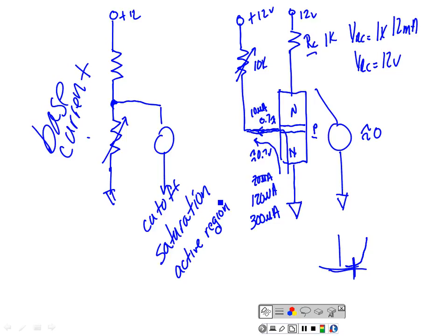But it's going to vary with temperature. So the ratio between the base current and the collector current varies with temperature. So we'll talk about some of the things we do to help get rid of that variation with temperature. We've got different ways we can bias the transistor so we can just about ignore temperature. We can ignore beta. We can ignore this ratio. Is everybody okay? So this is real neat.